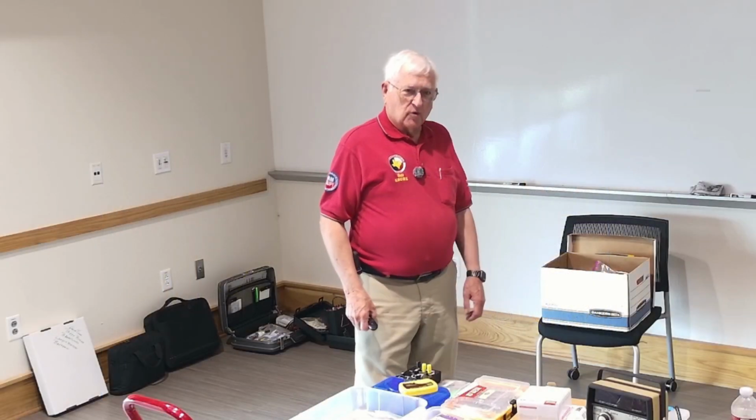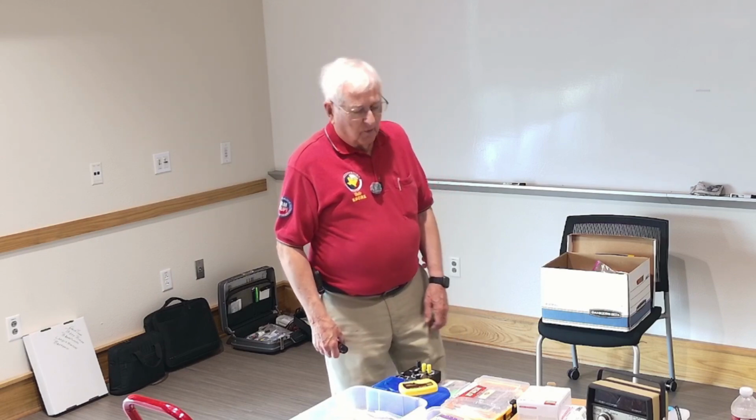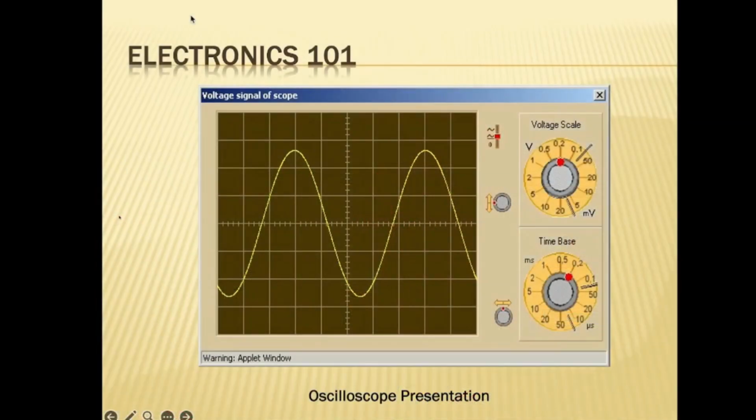This is where the plot starts to thicken a little bit. On an oscilloscope, we basically get a good depiction of what an AC waveform is going to look like. There are 5 main controls that you need with an O-scope. The first one is the voltage control. The voltage control controls how much that little square between that line and that line, how much voltage that represents.